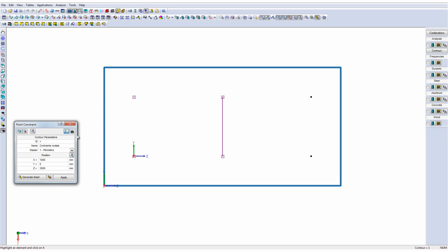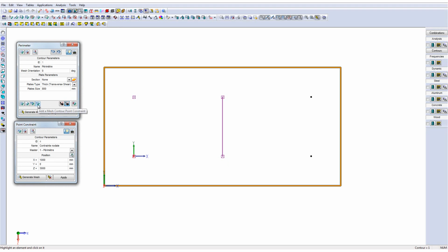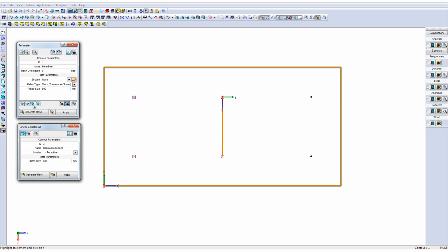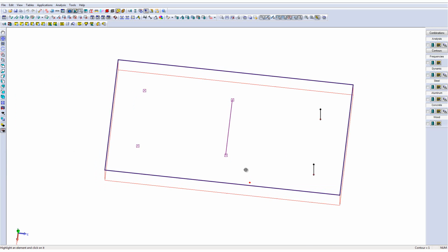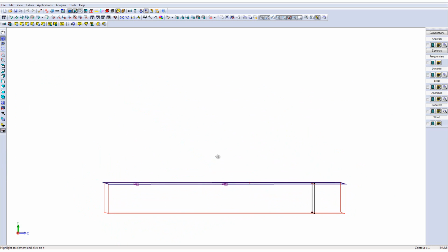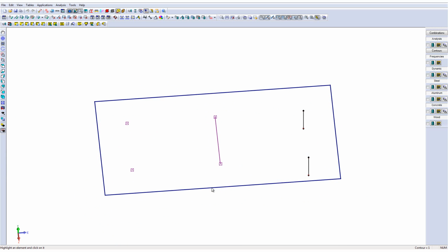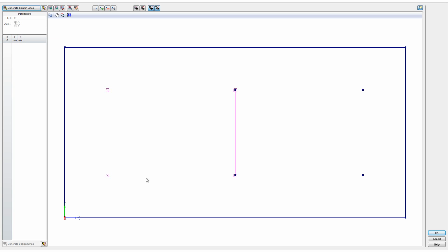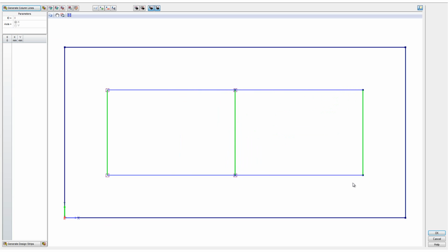The point constraint can be placed in the model directly from the Finite Element Mesh Generation menu. The linear constraints are added from the same menu and can be used to represent a wall in a model. They are detected as support on both ends of the linear constraint. If you already have supports defined by members perpendicular to the slab that are already defined in the model, this will also be detected as support. In the interface of the assistant, we can see that the supports are displayed by different symbols, but will be detected the same way.